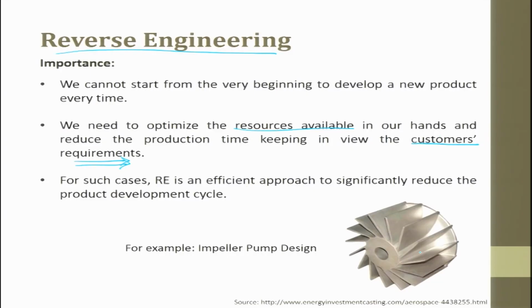From the data you try to make a 3D model. The 3D model you give to CAM, then you start machining it and getting the data. So, all these things in reverse engineering could be accelerated because it is in digital form. The moment it is digital, I can modify the data, or I can filter the data to get what I want exactly and then start using it.